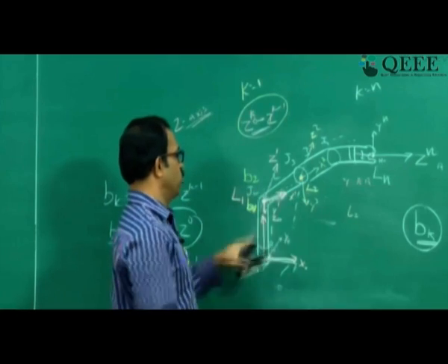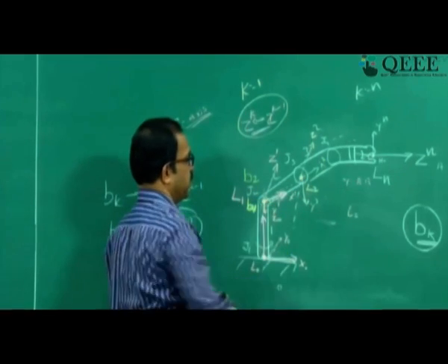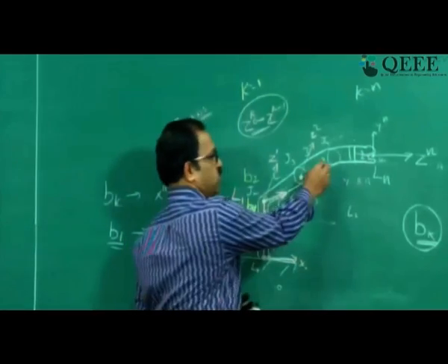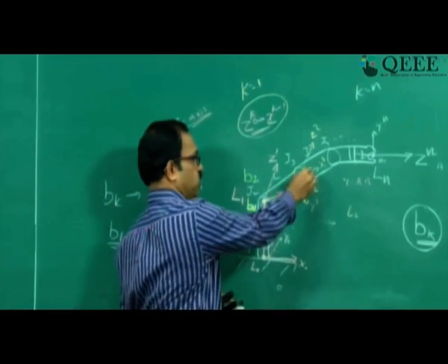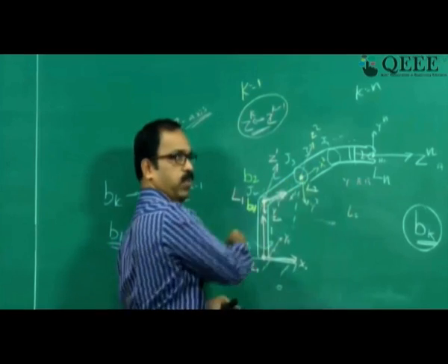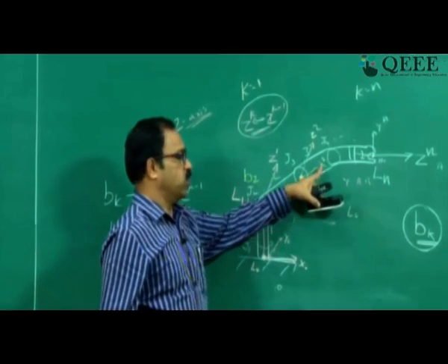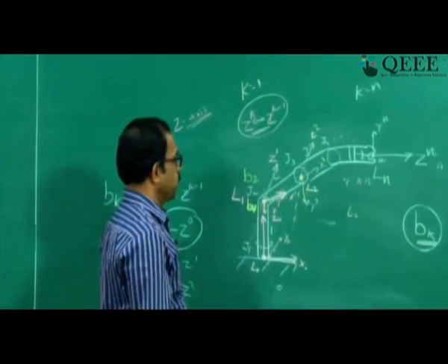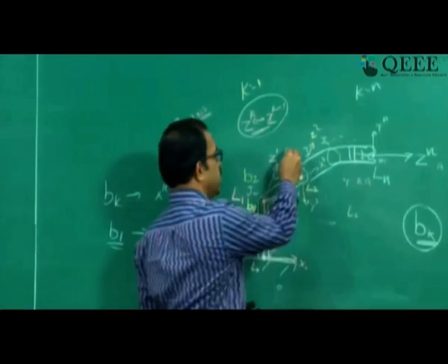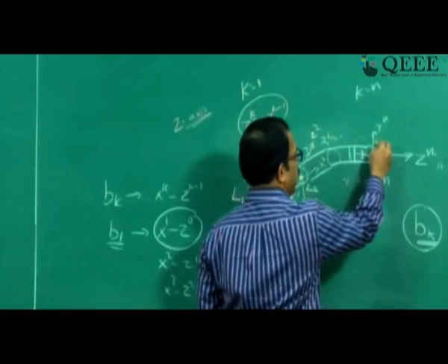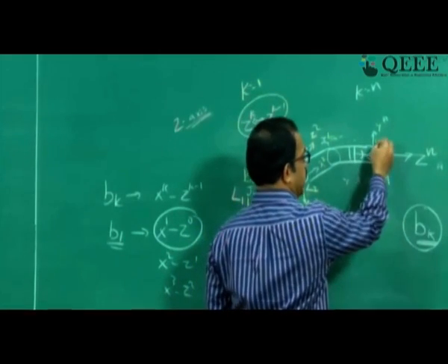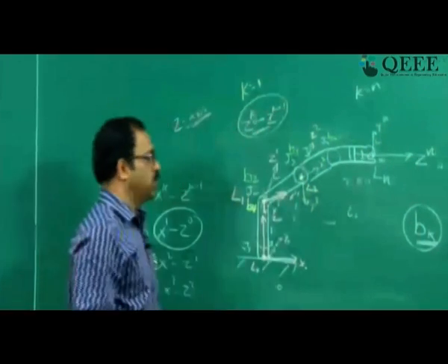Another important point when we assign the x axis is that it should always point towards the previous joint. So x2 should always intersect with the previous joint, which is one consideration for assigning the x axis. Similarly, you can identify b3 here, b4 here and b5, depending on the number of joints. So bn will be at the tooltip.